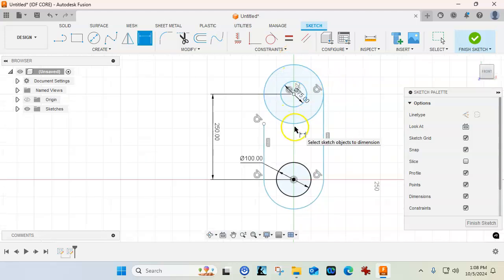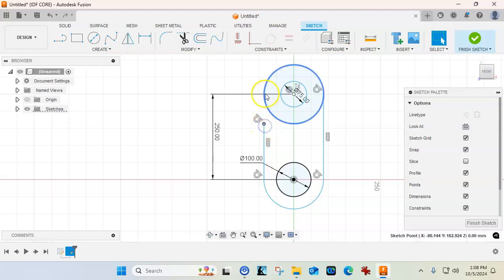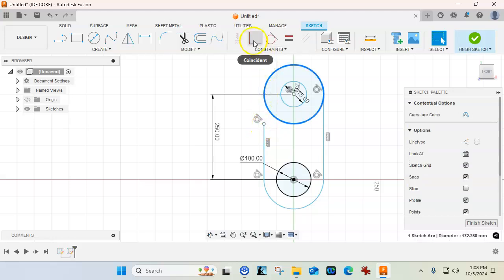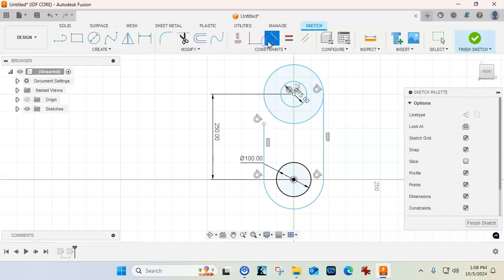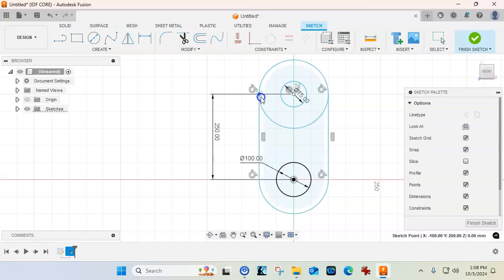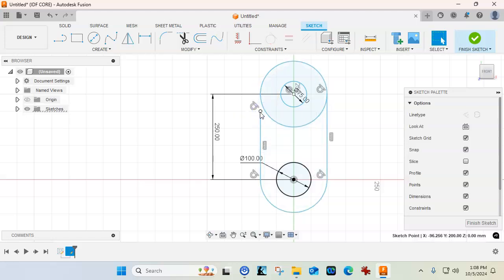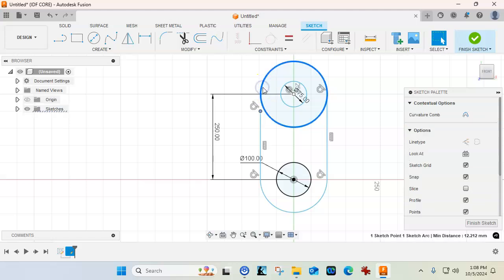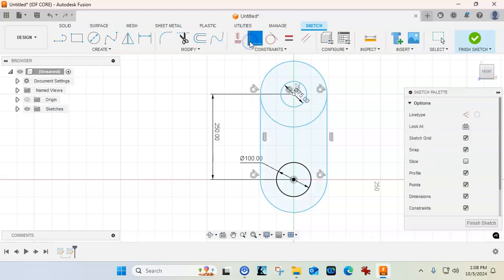One of the reasons I wanted to do the circle was to have it be able to go coincident and then go tangent. So if it still moves, it did not stay coincident. There it jumped. All right, so let's put in some more dimensions, and we're going to keep working toward it.